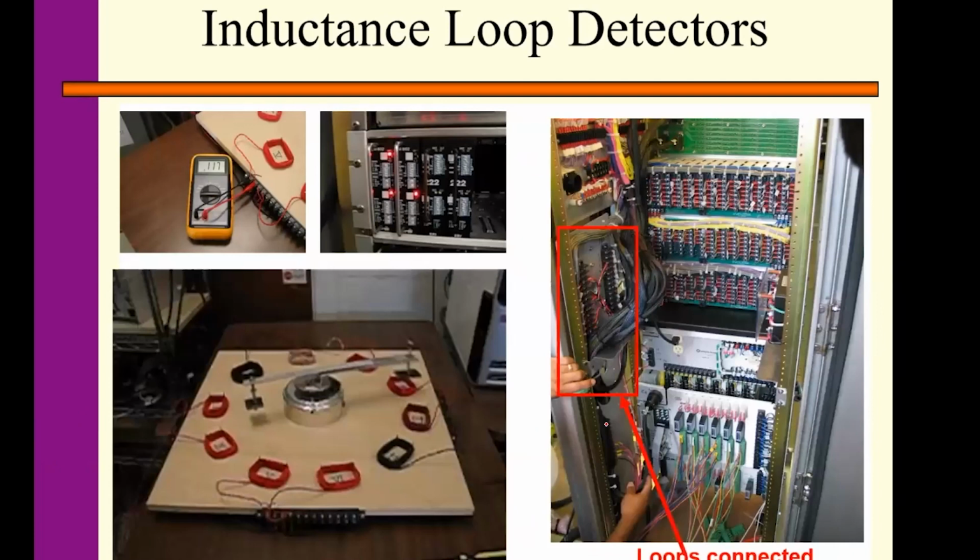And so this is the overview of the loop sensor input to the controllers. This is the control cabinet. Like I showed you on the first slides, at intersections, if you pay attention, you see this control cabinet. This is the back view of the control cabinet, and you see the input output facilities. When the loop sensor data is generated, it goes to the input facilities, then to the detection card, and the detection card converts the data into a signal and inputs it to the controller.